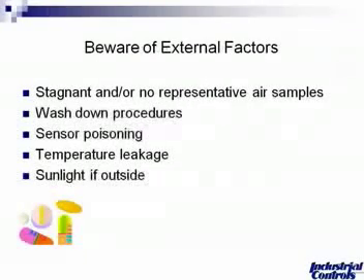When you want to measure humidity and place your humidity sensor, you want to be aware of several external factors that you need to keep in mind. If you have a large room that you're trying to measure and get an accurate reading of relative humidity, airflow is critically important. You don't want to place a sensor in the corner of a room if your product or material that's important to you is in the center of the room.